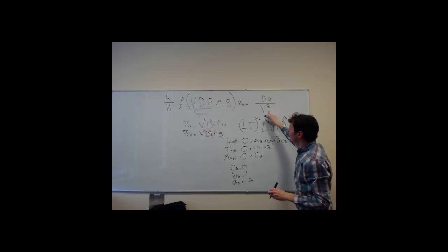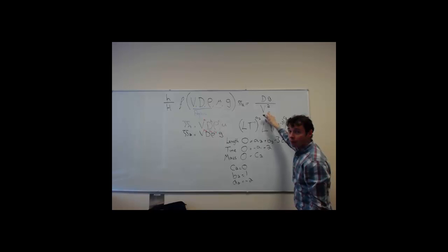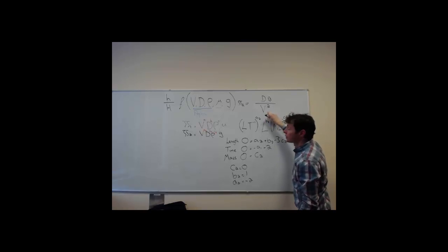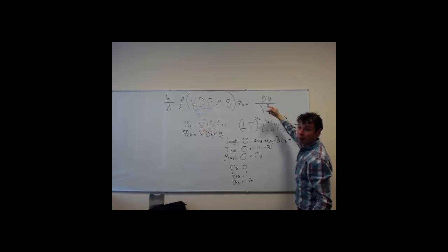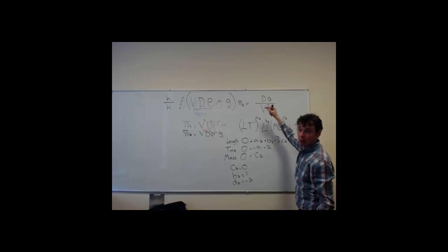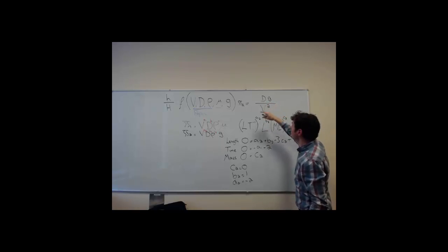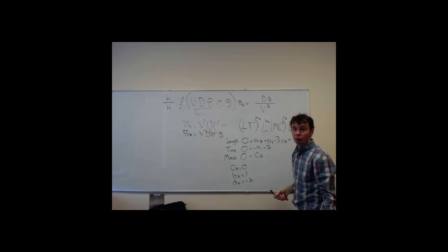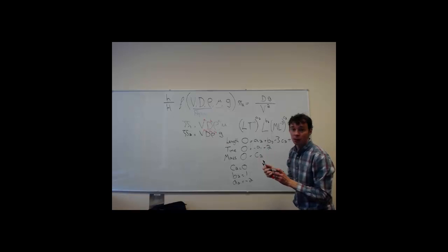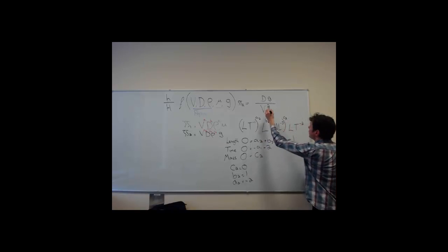Now, this is actually a bit like the Reynolds number. Okay, but you notice it's not in the same form. So what I'm going to do is, because it's dimensionless, I can invert this, so I can flip it around, exchange the numerator with the denominator of the fraction, and I'm also going to square root top and bottom. Again, we're square rooting a dimensionless number, so that's allowed. We're doing the same, we're always keeping it consistent.